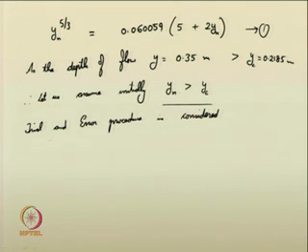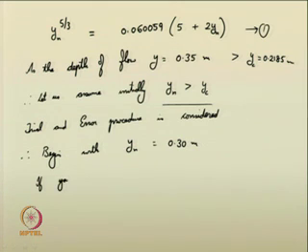So, therefore, to begin with, you can take any value of y n greater than y c. I am just beginning with y n is equal to 0.30 meter. Just want to see that. So, if you substitute in equation 1, y n is equal to 0.3, see whether the equations are matching or not.